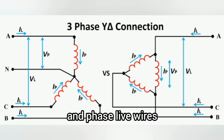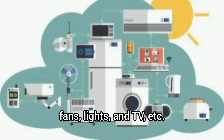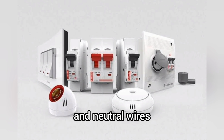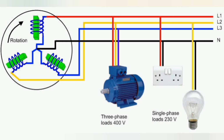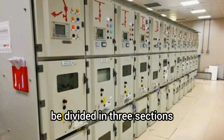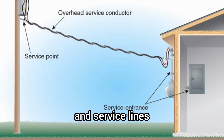Residential load, i.e. fans, lights, and TV, etc., may be connected between any one phase and neutral wires, while three-phase load may be connected directly to the three-phase lines. In short, secondary power distribution may be divided into three sections, such as feeders, distributors, and service lines.